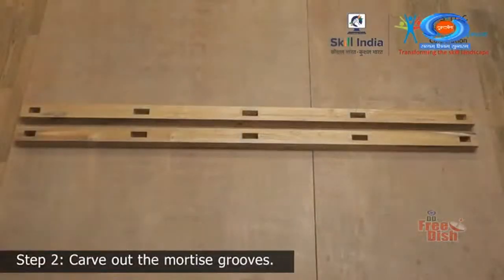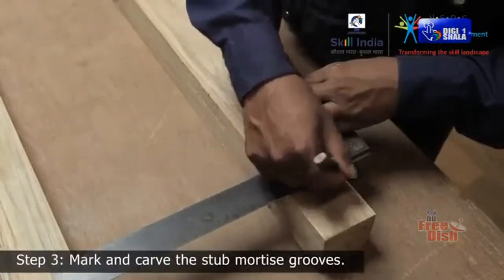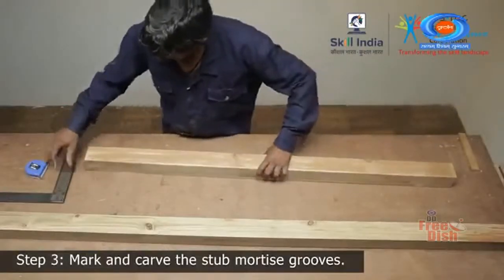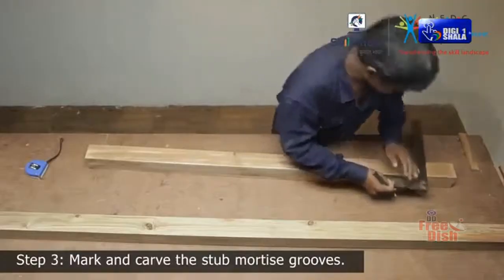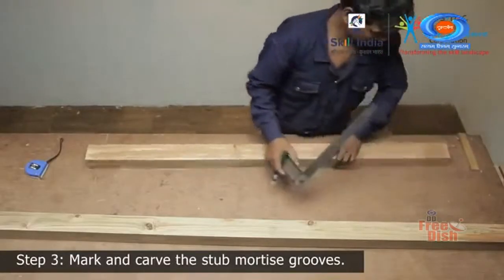Now, when you are done with the mortise grooves on the top and bottom rails, you need to carve in the stub mortise on the studs for the noggins to fit in. Step 3. Mark and carve the stub mortise grooves. Measure the position for the noggins on each stud and mark out all the lines on them. You will mark 12 such positions for the stub mortise on each of the 5 stud members as per the work drawing.